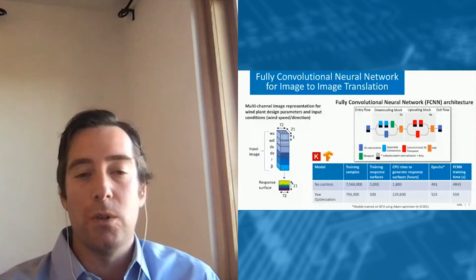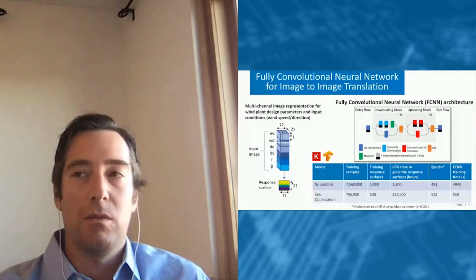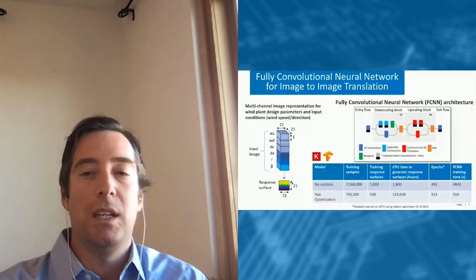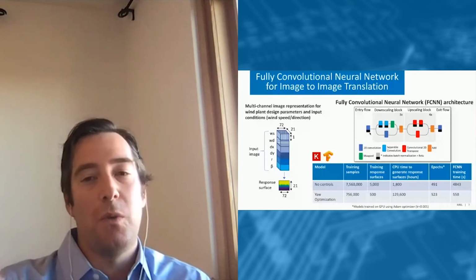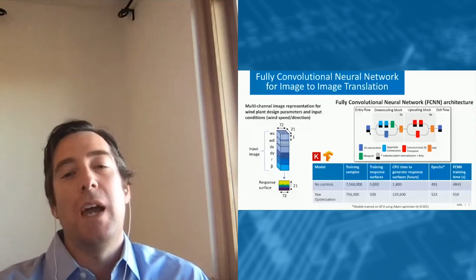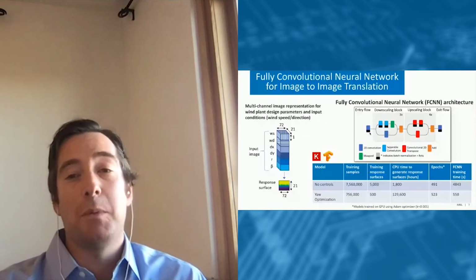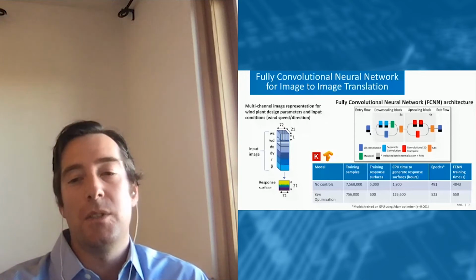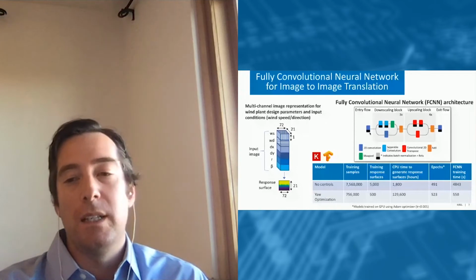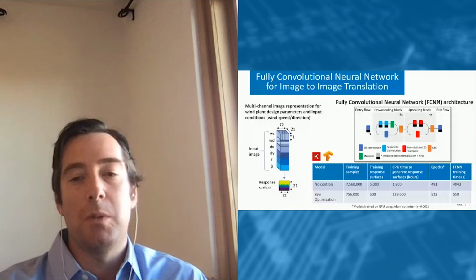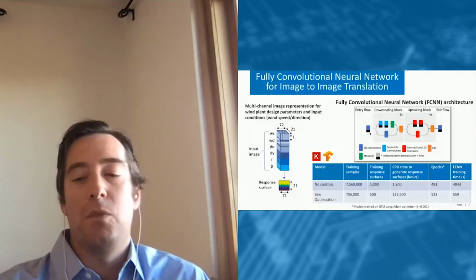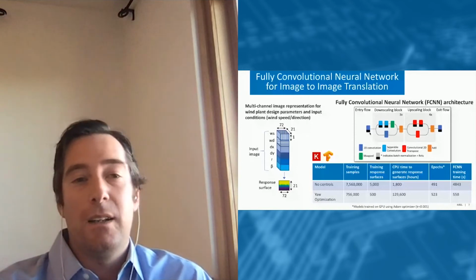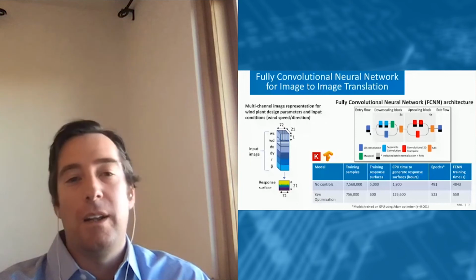One is for no controls. The other is for this wake steering case that uses yaw optimization. Again, wake steering intentionally misaligns rotors so that we minimize the effects of waking in terms of energy production. Computing this yaw optimization, even with an efficient model like FLORIS, is quite costly, and you can see that there's some big numbers there. So we had to parallelize these across our energy efficient supercomputer to generate these robust training samples. So the model does well when evaluated against test data, at least measured using mean absolute error and MSE.